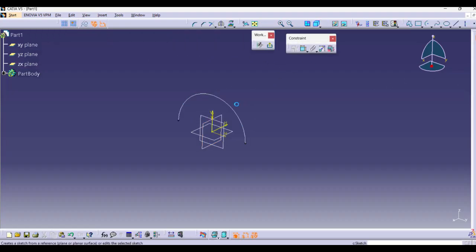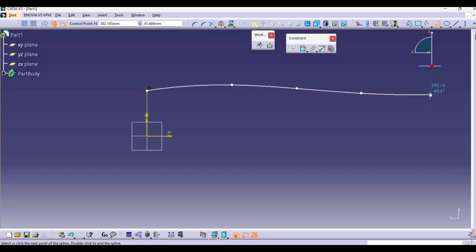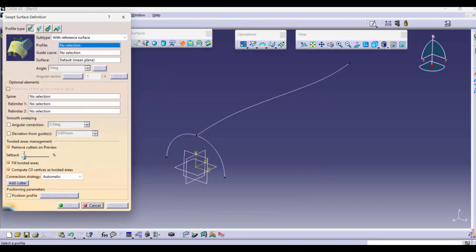Next thing we require is path. Here we are going to add one path by using spline. We can use spline, arc, line, whatever thing we require at that time. So I am going to select this spline here. But to start with the profile, we don't have any reference of the profile here. So we'll select the profile first and say project entities. So we'll get the reference point or starting point. Next we'll put up this construction here and go for this spline command. Say escape. So now we have one profile as well as one path.